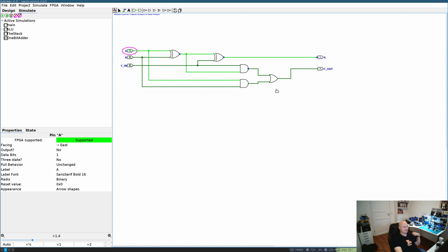That's XOR, AND and OR gates, 3 gates, and you first change the input of XOR, so the input of AND changes with a delay of 20 nanoseconds, so the output of AND changes with a delay of 20 more nanoseconds, the output of the OR changes with a delay of 20 nanoseconds,